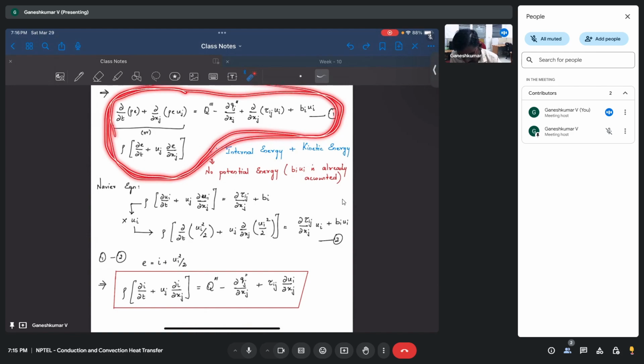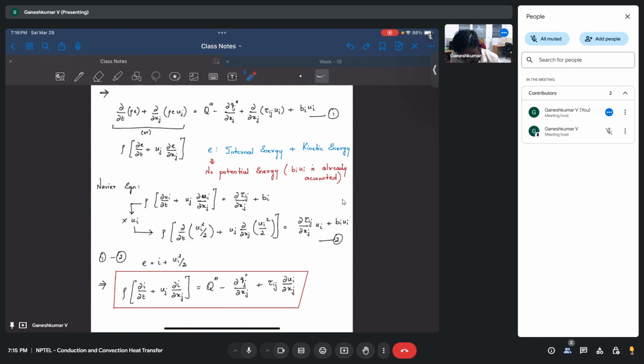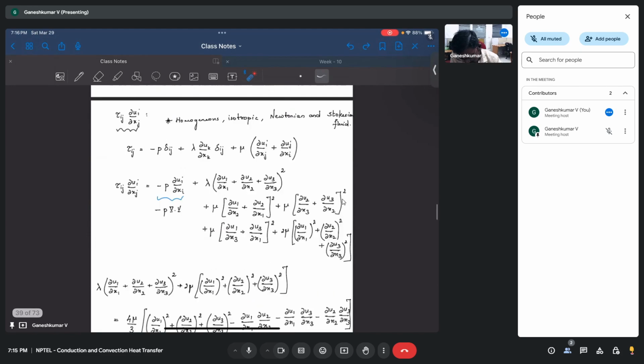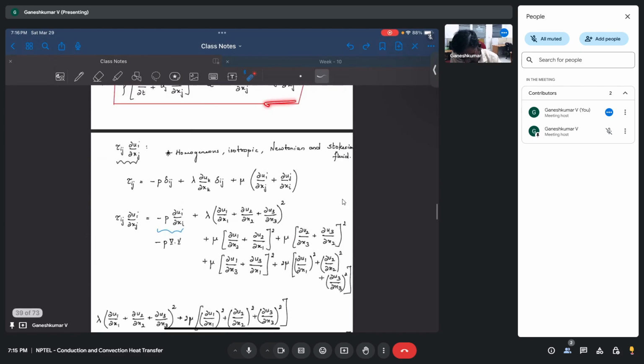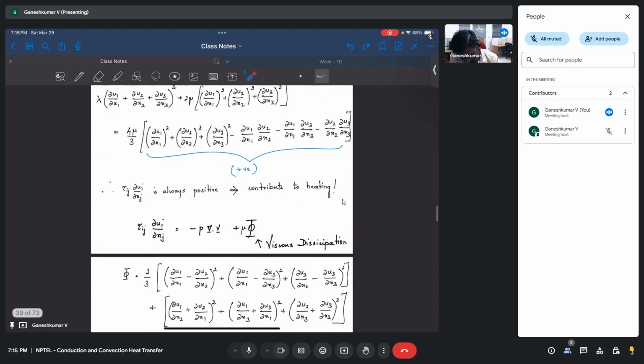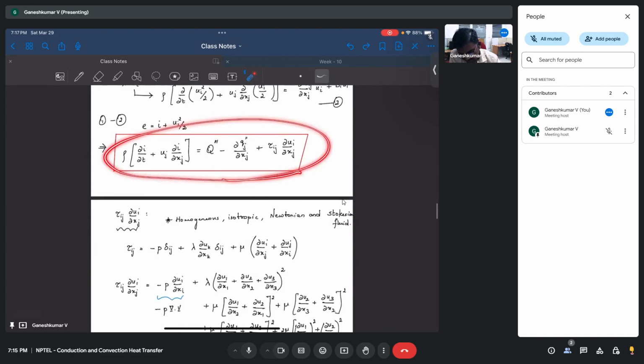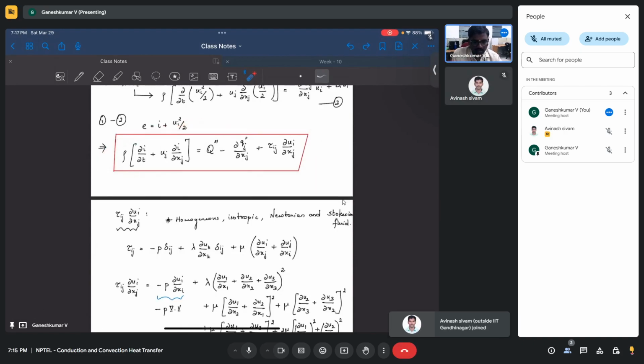Right? Now you can express this in terms of the internal energy equation, and also in terms of enthalpy. But anyway, this part is nothing but PdV and viscous dissipation, right? So this is what this part is. Now you can use your Eckert number, which is U squared by Cp times (T minus T), or delta T basically.